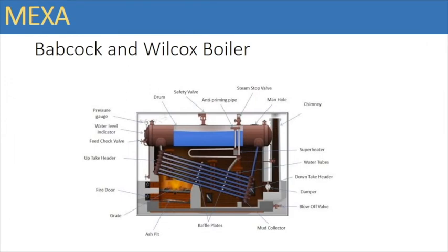The Babcock and Wilcox boiler was invented by George Herman Babcock and Stephen Wilcox, hence the name. This is a horizontal drum axis, natural draft, natural circulation, multi-tubular, stationary high pressure, externally fired water tube boiler. This is used in steam power plants.